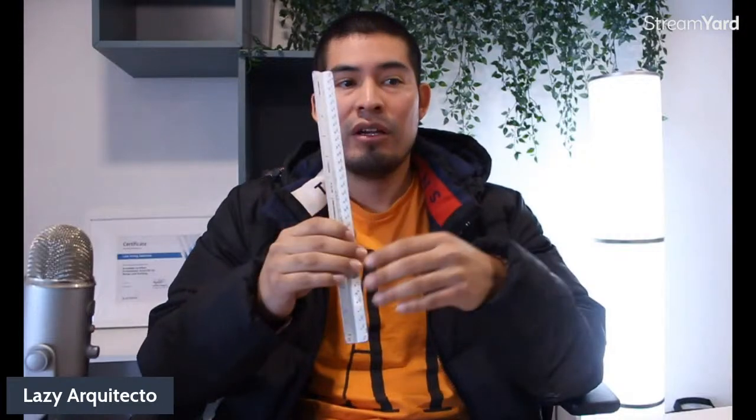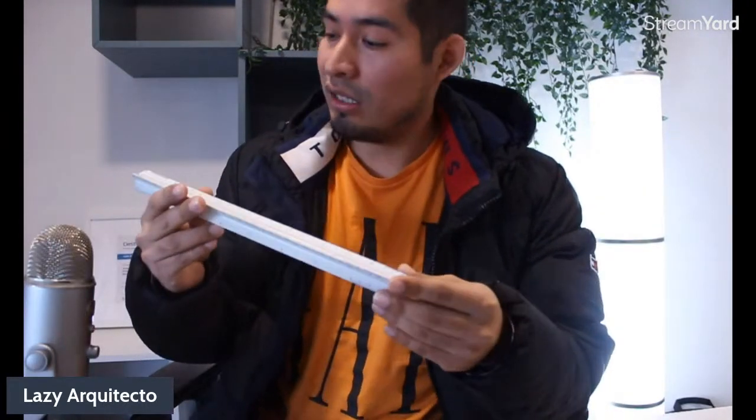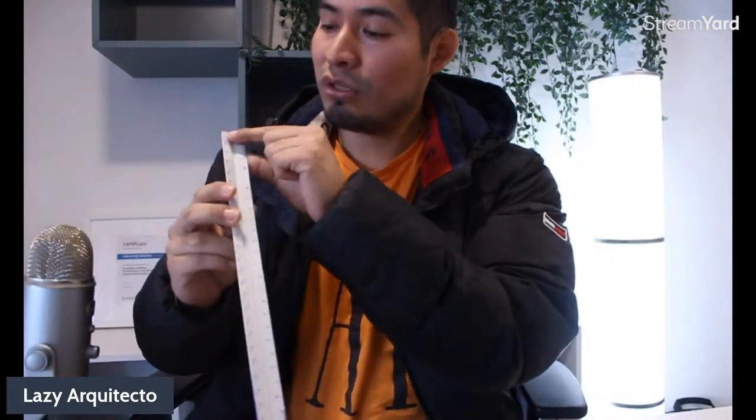And what I was saying from the viewport is you need to pick a scale that is most used, so that whoever receives your drawing and prints it, let's say to the correct size of your sheet, in this case 24 by 36 inches. Let's say if I pick a scale 1/4 over here in AutoCAD, this person, when he prints the drawing, can use a scale like this and find the 1/4 over here.